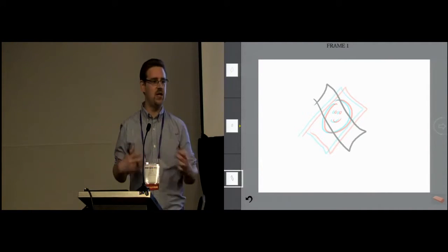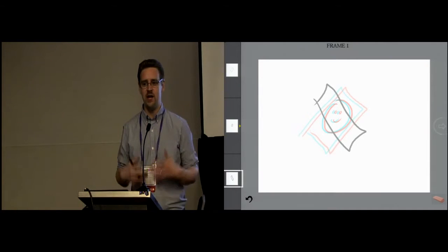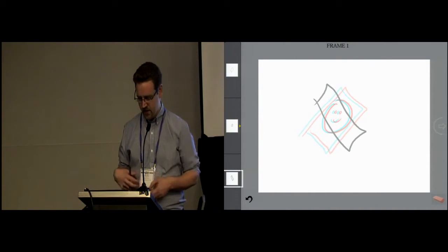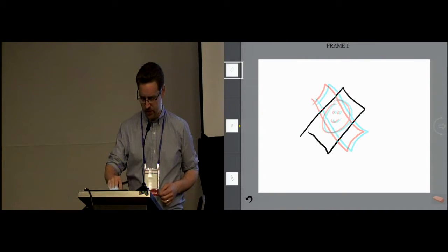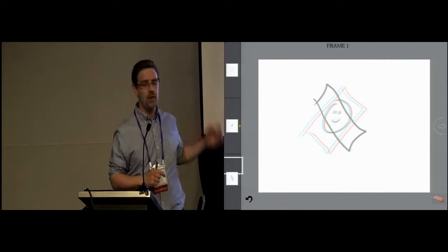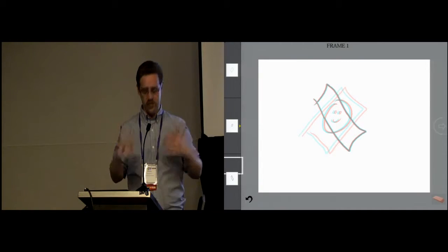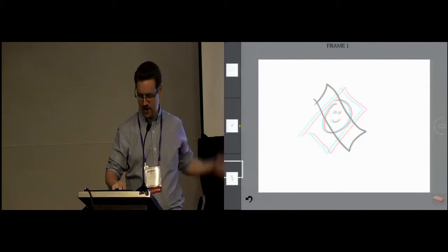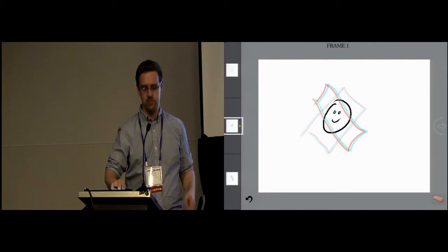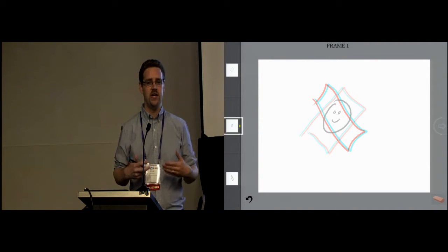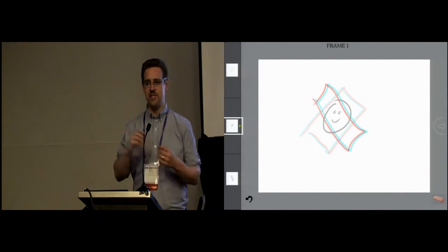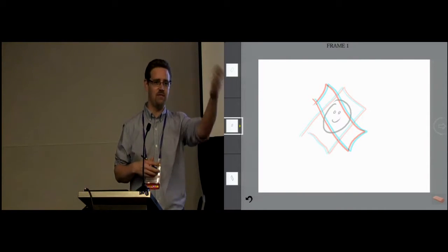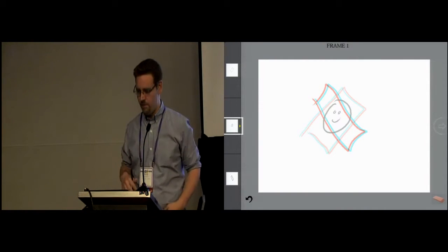And so very quickly, you can build up a stereoscopic scene in live time and have these discussions. The other thing I want to mention here is that as I'm moving the slider, you may notice, it's probably easier to see without the glasses, that I constantly change the image on the screen itself so that your current depth plane is always at the depth of your pen. This ensures that the lines that you create with your pen appear under the pen rather than floating way behind or on top of where you're trying to draw.